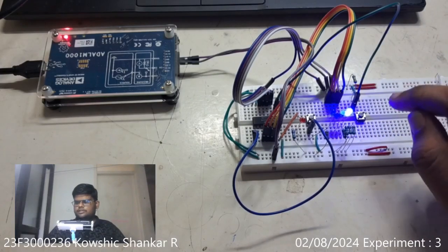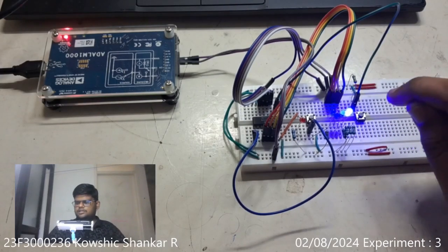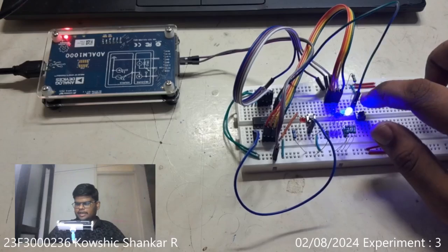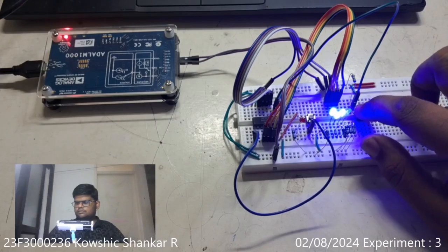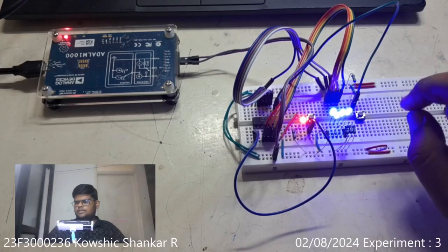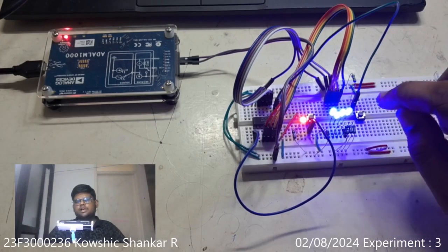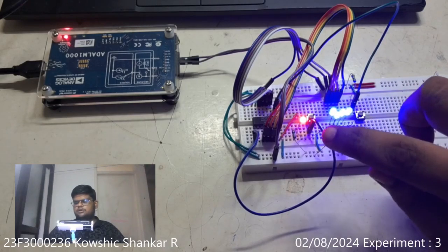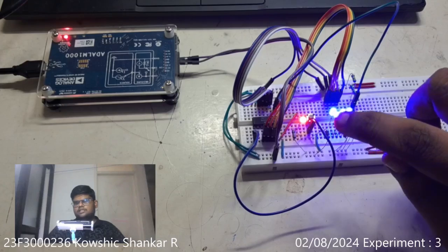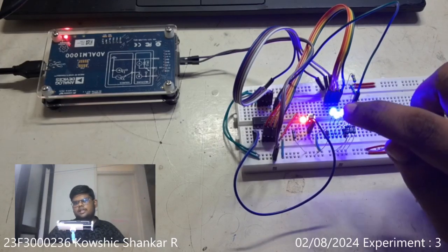You can see that after giving a pulse, the counter adds a 1 and displays 1 in binary. Like this, it counts up to 15 and on the 15 the RCO turns high, as it would be useful to ripple carry the output.